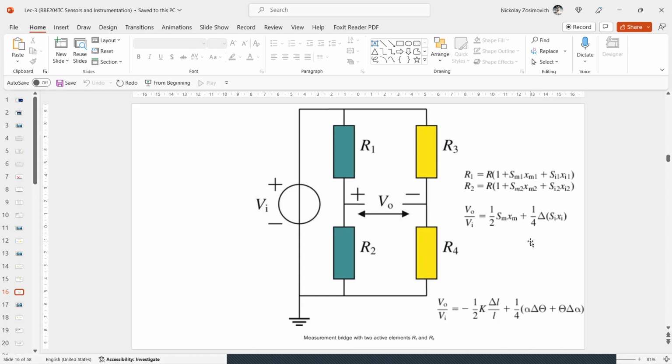So if both sensor parts have equal sensitivity to interference by symmetric sensor design, and both sensor parts experience the interference equally, the error term in our last equation on the bottom should be equal to 0, and the interference is completely eliminated. That's nice. So this last equation is useful to make a quick assessment of the error due to the asymmetry relative to the measurement signal.